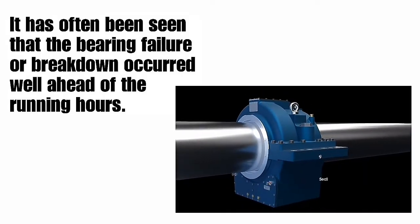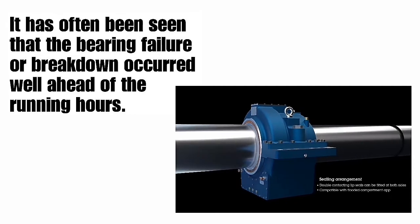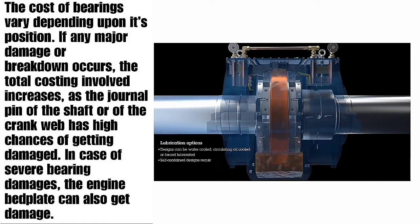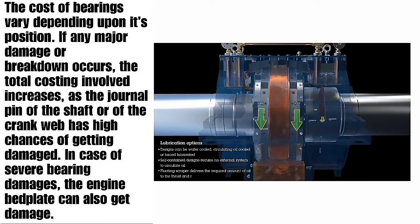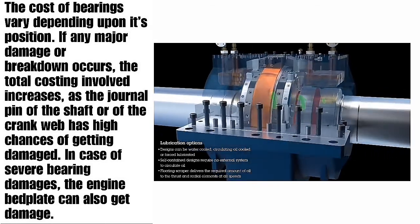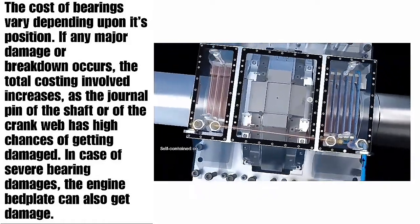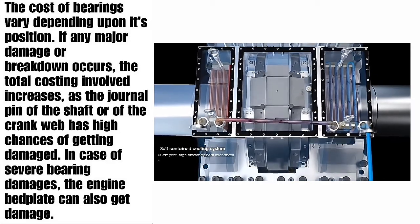It has often been seen that bearing failures or a breakdown occurred well ahead of the running hours. The cost of bearings varies depending upon their position. If any major damage or breakdown occurs, the total cost involved increases, as the journal pin of the shaft or the crank web has a high chance of getting damaged. In case of severe bearing damage, the engine bed plate can also get damaged.